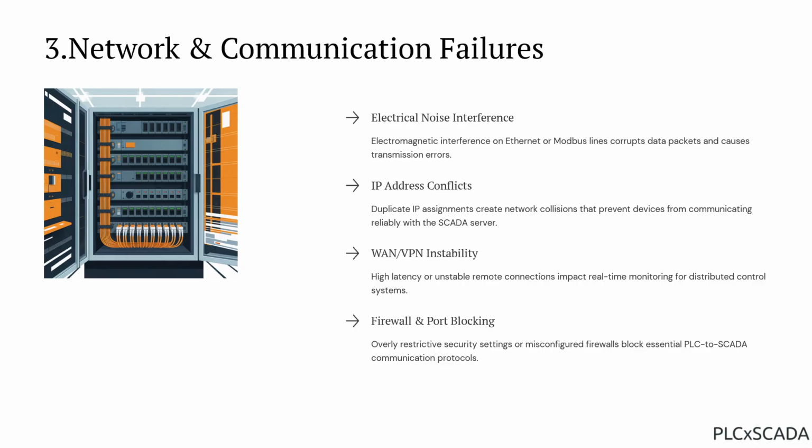Next is IP address conflicts. If a duplicate IP address is present in the network, it may bring down the SCADA automatically. Also, a weak and unstable WAN connection may hit the real-time monitoring aspects of the SCADA.